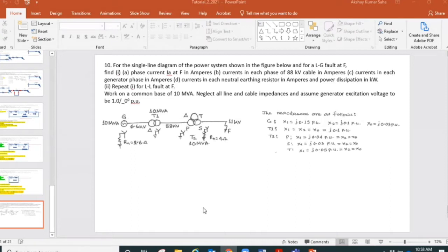It's not power system, but I am okay with spending a few minutes here. You see two windings are star connected, but if we go back to the transformer T1, we see that one of the windings is star connected, the other one is delta connected. So you will see in most cases, when you design them, in a two-winding transformer, at least one of the windings is delta.